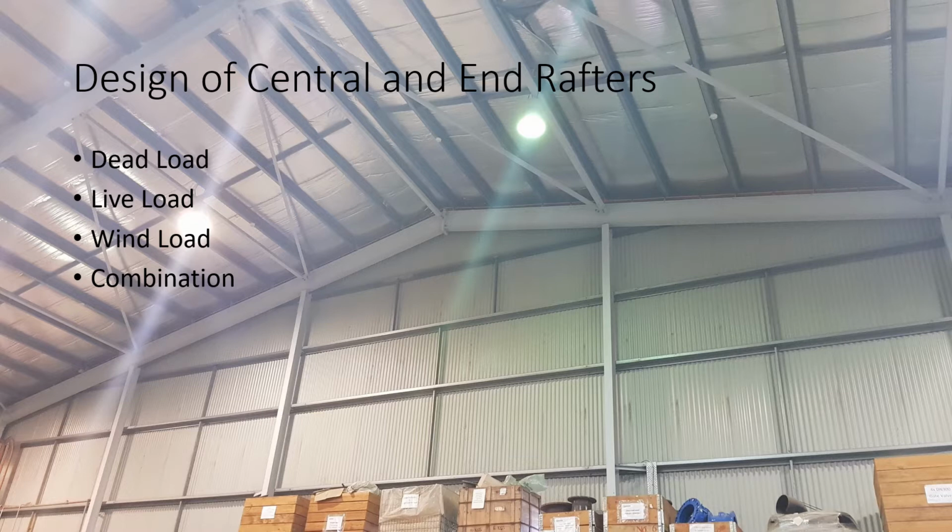The reasoning for why the central rafter type is larger is due to the central rafter supporting twice the area than the end rafters. Due to this, the central rafter is under more deflection than the others. Compared to other alternatives on the capacity tables, this choice gives adequate safety whilst also having the lowest weight compared to the others, making this the best choice for rafters.